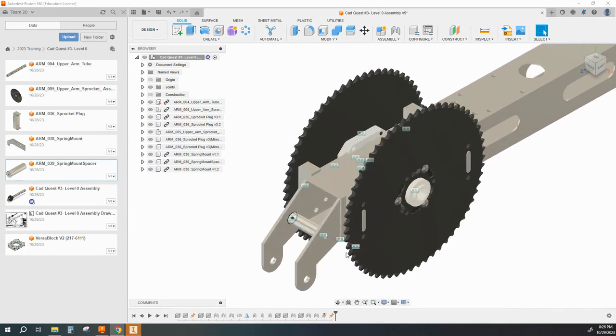So it may be nice while you are working to turn those off, which is as simple as coming down here to Display Settings and looking at Object Visibility, and here you can uncheck joints. You can uncheck lots of other stuff too, but in this case I just want to turn off the joints. And next time I want them back, if I want to be able to again look and see what's joined to what and with what sort of relationship, I can just go back down here, find it again, Object Visibility, turn joints back on.